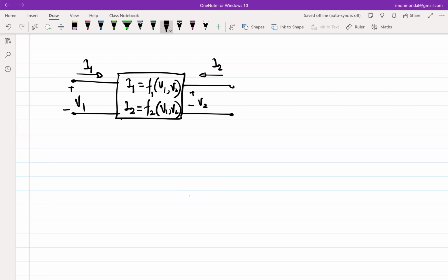Okay, so now we are all experts in analyzing Taylor series for a single variable function. Now this is a multivariable function. Nothing changes, just that I have to do partial derivatives with respect to whatever the dependent variable is. So in this case, I1 is F1 of V1, V2, right? So let's say this is I1Q, V1Q, V2Q. Q refers to the quiescent point that has been set up somehow. We have a battery somewhere inside, outside, but it has been set up somehow.